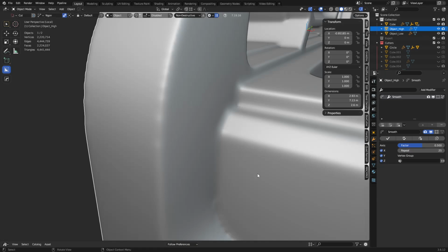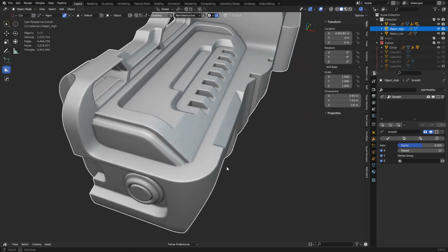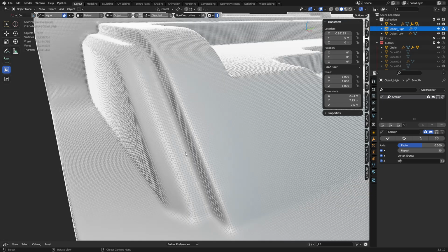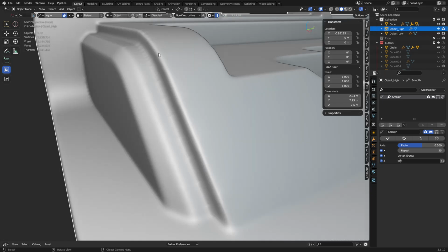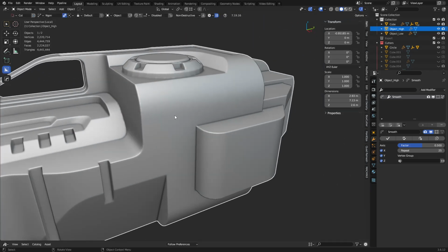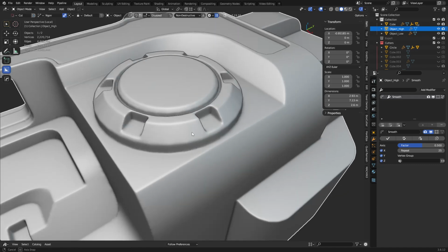Even if you remeshed it, it would still be there like that. So the solution to that problem, the best I found anyways, is that if you just use a higher density mesh and just smooth more, it tends to work it out better. It doesn't make it perfect, but it does work it out better. And so you want to use this in specific